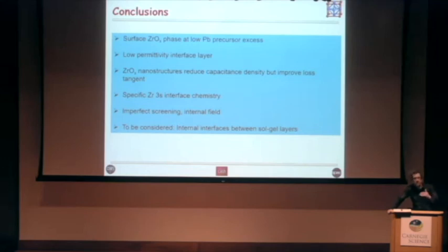So what goes down first is titanium-rich, so at the bottom of your layer you will have PTO, or almost PTO. So in fact, what we're looking at in that seed layer is the growth of PTO on platinum, rather than PZT. So this may have something to do with it. Might want to talk later.